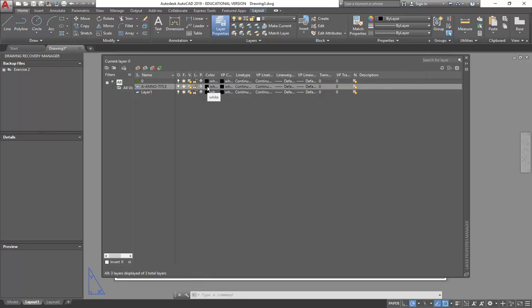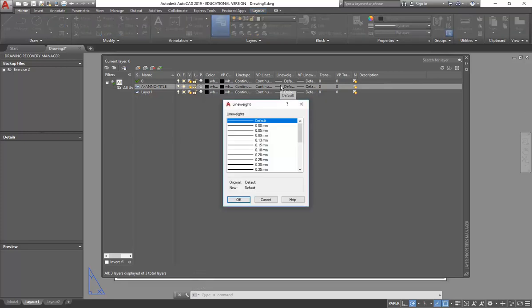Okay, what line weight? For text, you don't want it too heavy, but you also don't want it too light. Depending on what it is, sometimes dimensions you'll take down to even 0.15, but regular text and lines on your title blocks you might have up to 0.25, so you will have a couple of different line weights.